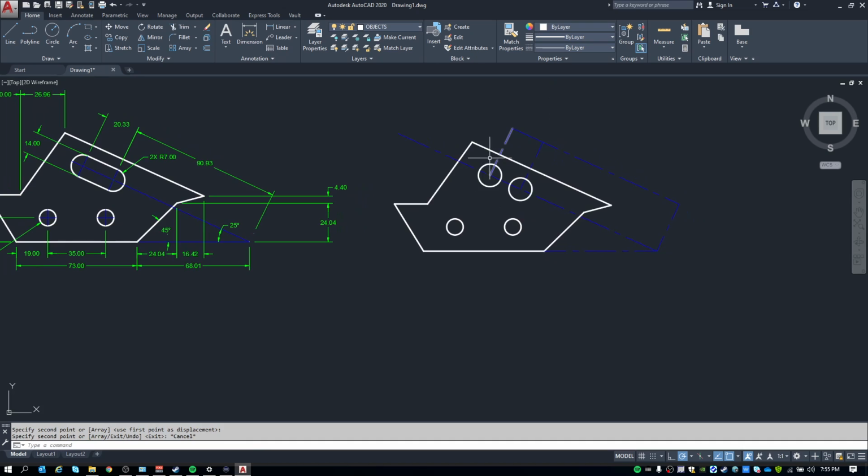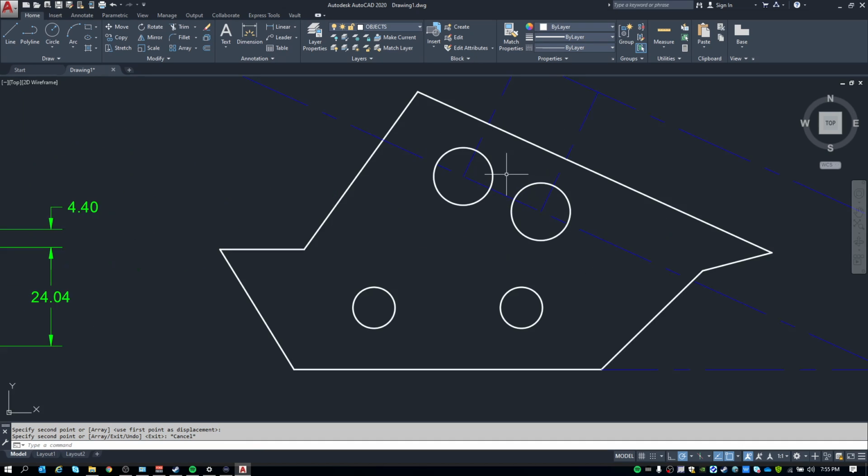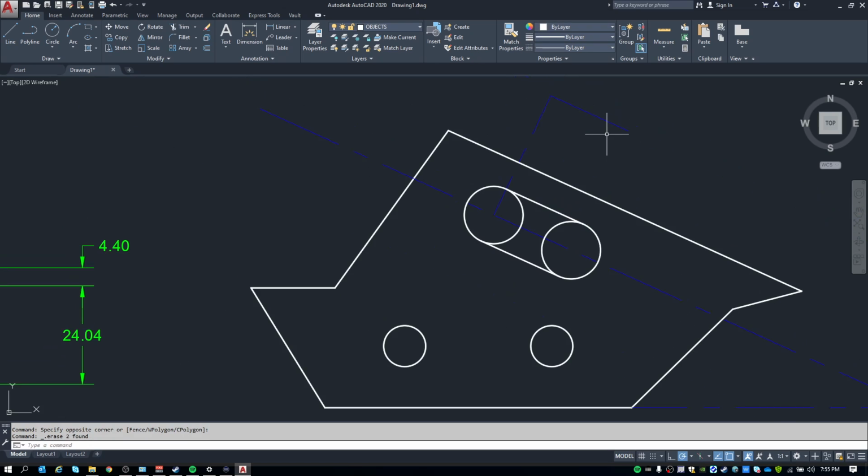So basically that's going to be the two sides of the circles. So because we drew these reference lines, we know if you come off of those perpendicular, it's going to snap to the tangents, each of the circles. So that one's easy. And then from there, you can use the mirror command and use this center line as your reference for your mirror. And you're done with that.